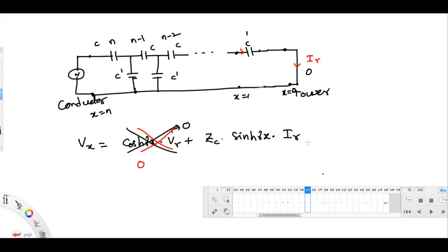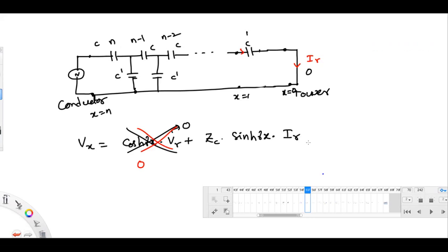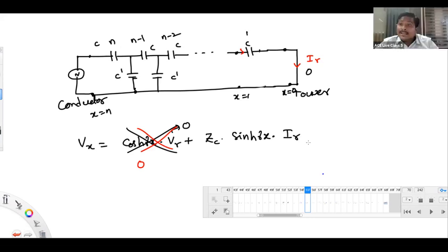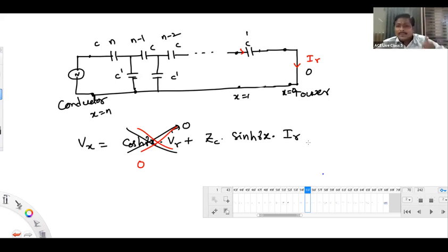Okay, sir. But as you said earlier, sometimes there is an over voltage at that place, sometimes there is under voltage. How to tackle both with the same device? You go with a device called a static var compensator, SVC, where we will have a combination of capacitor and reactor. Yes, sir. StatCom also there, no, sir? StatCom is also an application. Yes, definitely. StatCom is also one of the applications.